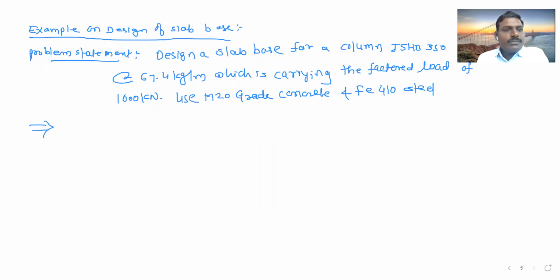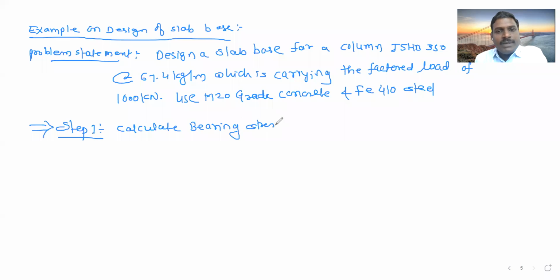Step one. What is step one? Please see the procedure. Calculate the bearing strength of concrete. We have to use M20 grade concrete, so we have to calculate how much bearing strength that M20 grade concrete has.